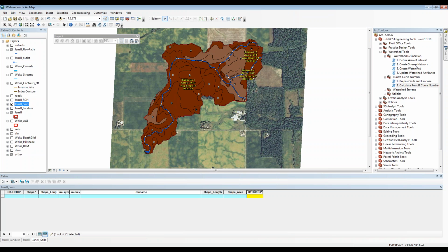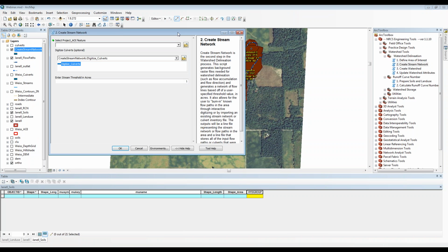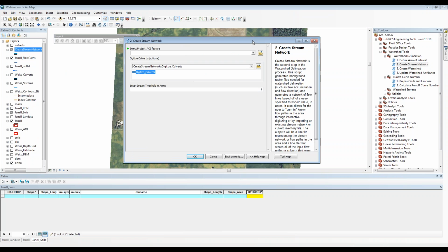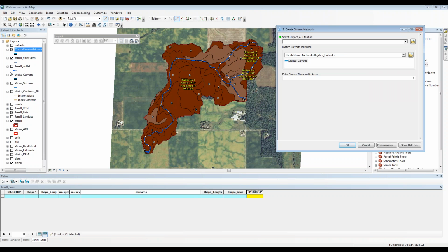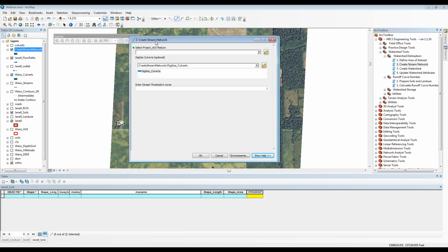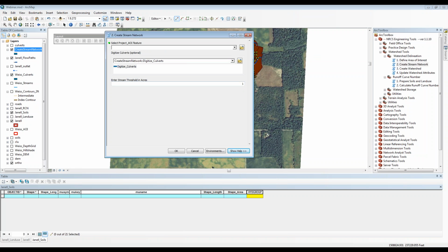If your mistake occurred with specifying culverts, if you didn't do a culvert, that actually affects your watershed. So here we go. But if I failed to digitize, where are my culverts? What if I failed to do this culvert, or even this one, and it ran the water through the ditch over into my watershed? I'd have to start back over here at this step to update my stream network to get that right.